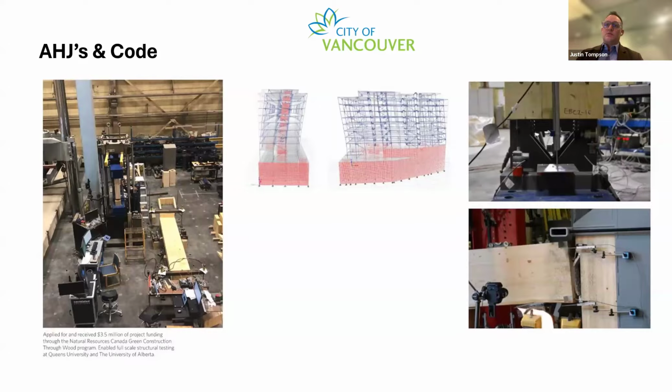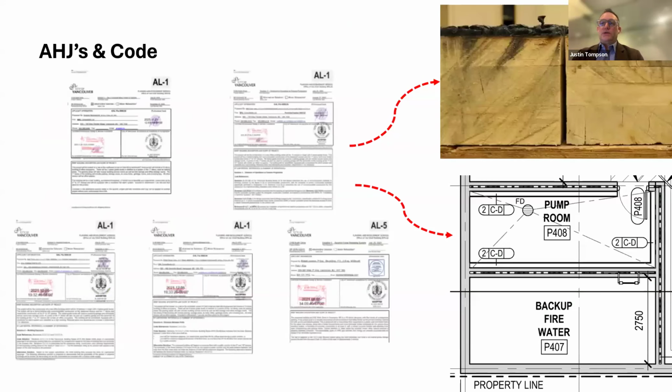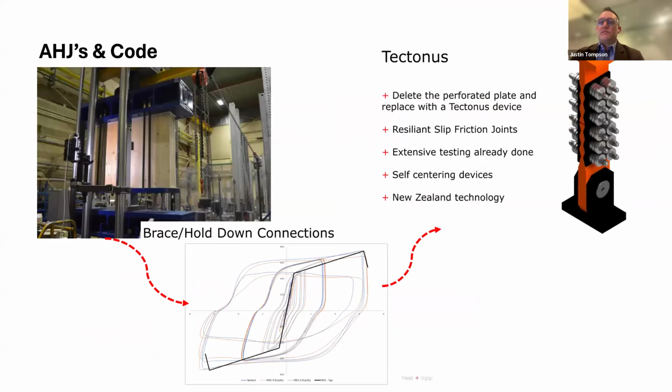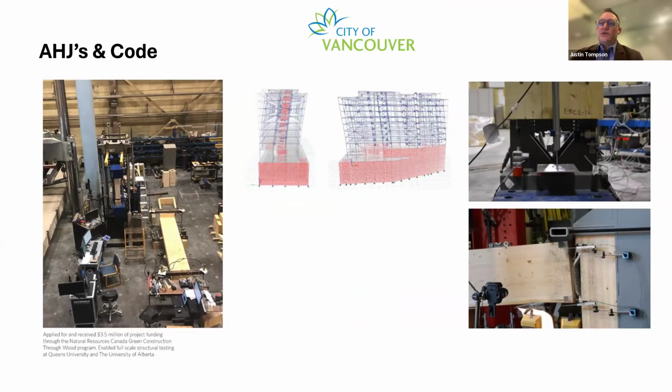So there wasn't anything very unique about the mass timber element of this. But on the building permit side, that was a completely different game. The city really had very little context. The code hadn't changed, allowed for multi-story unencapsulated, and we were going to 10-story unencapsulated, which the city hadn't seen before. So we had to engage both modeling and research on historical data. We had engaged Dr. Stephen Kraft out of Ottawa, wood specialist, who scoured through data from CSA tests from the past to see if there's anything there. A lot of it wasn't fully applying. And so we actually had to do a lot of testing ourselves.